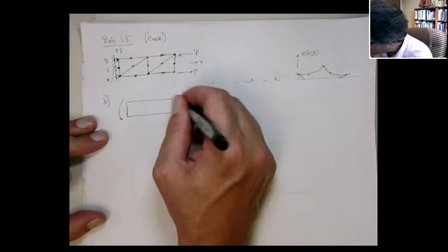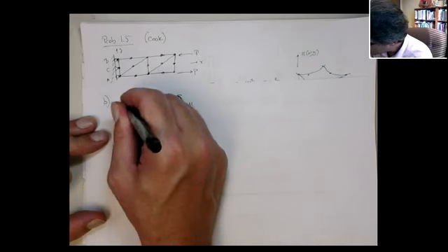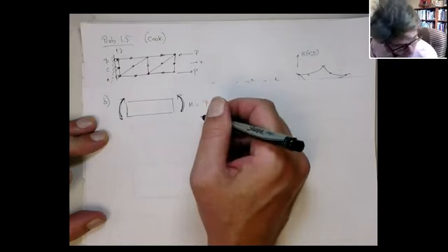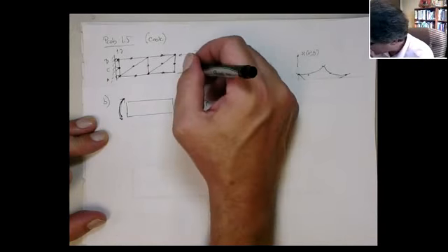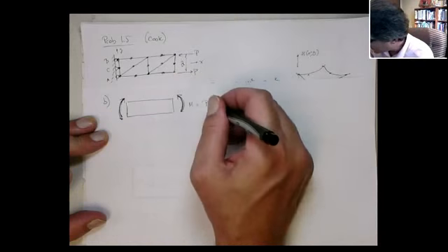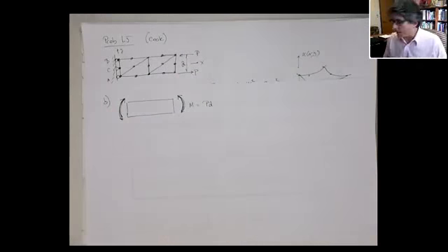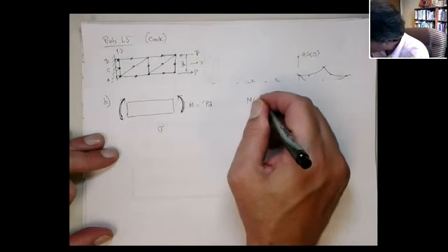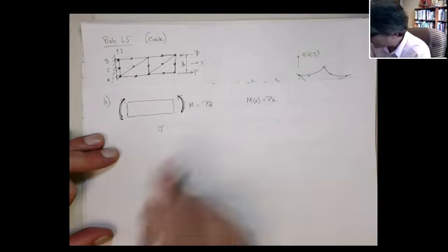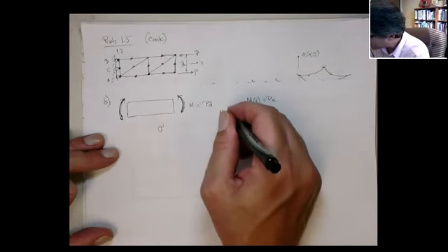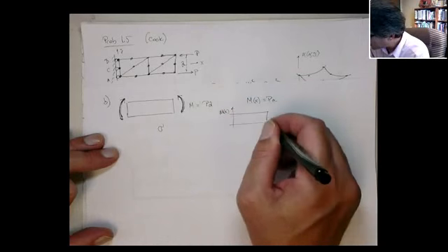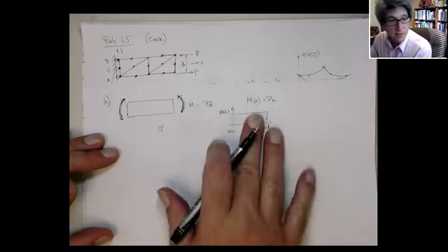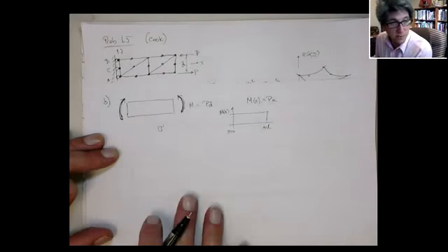I got the moments going the wrong way. All right? Where the moment is equal to P times this distance. Call that A. All right? That's the applied moment. And in that situation, we know that the moment diagram is constant. It's just PA, okay? So it looks like this. Right? Where this is x equal to 0, x equal to L. Again, this is for the exact solution, and we're going to see if we can reproduce some results like that with the linear strain triangles.